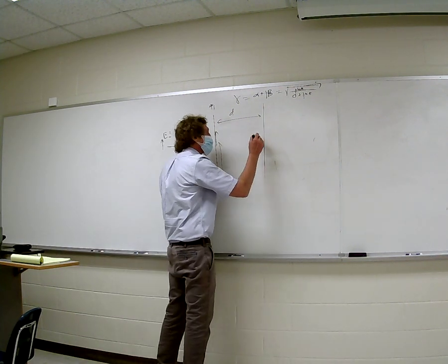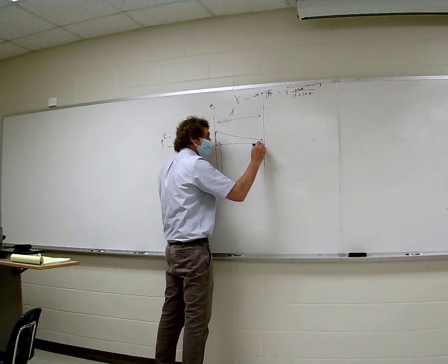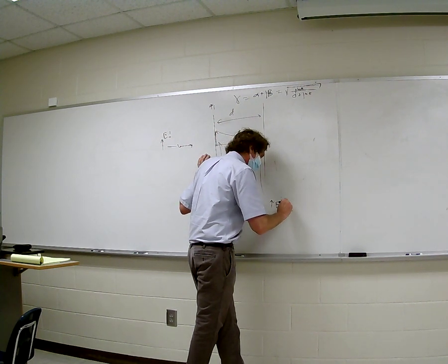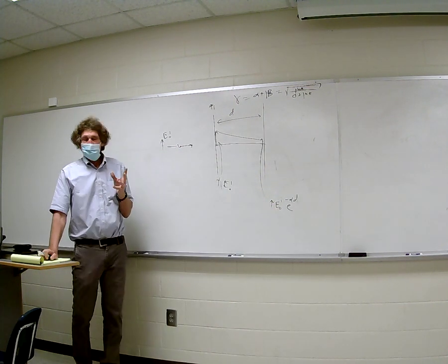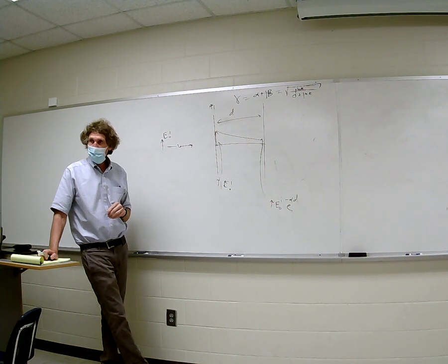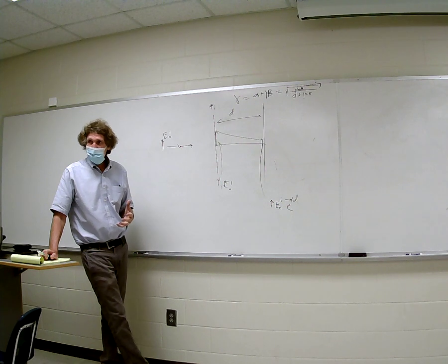Now, if that's the case, you're going to have an alpha value. The electric field strength, after it propagates through here and is reduced by a factor, will be tau E naught incident times e to the minus alpha d. Dr. Wentworth's book always puts gamma there, where you get alpha plus j beta, but beta doesn't do a thing. Beta is a phase. Don't worry about it. You got me on this?